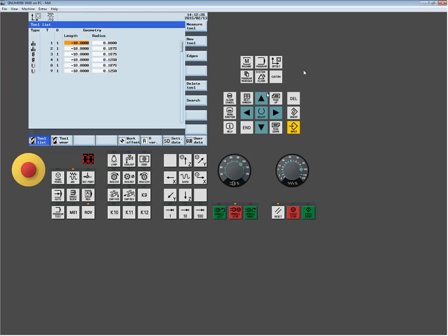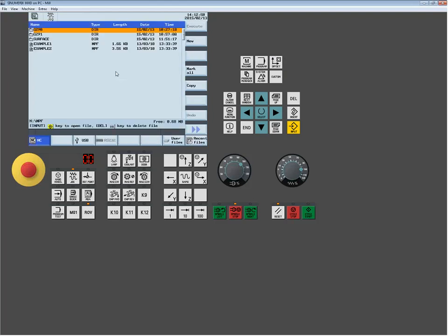Now I'm navigating through the different screens with this keypad on the right side of the display. You're going to see my mouse kind of hovering over it. With that, I can navigate back to the machine area. That's my jog screen, by hitting machine. I can go right to whatever program was last edited with this program button, or for what I'm doing right now, I can select the program manager button, and that's going to get me to the area where all of my part programs exist.